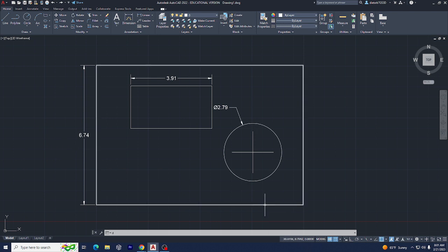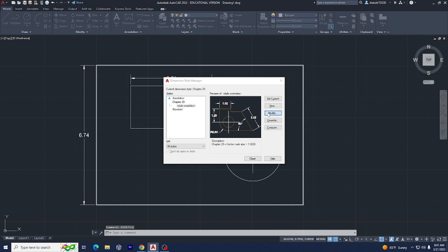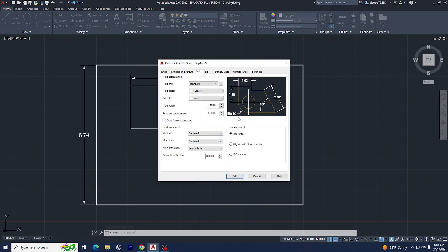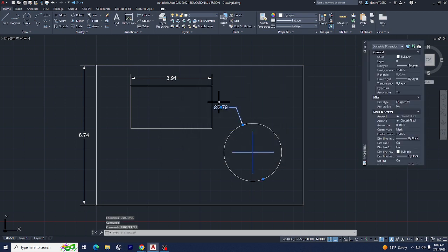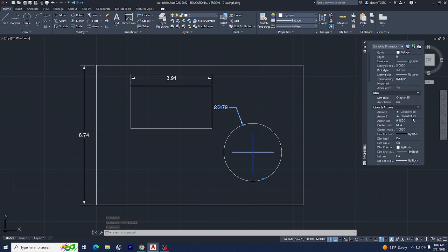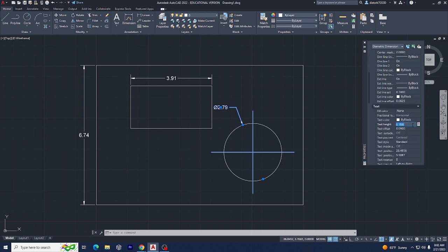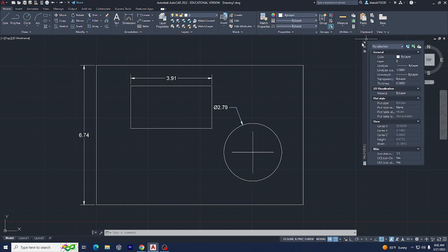So when you go to the dimension style and you go to modify, this changes it for everything in the drawing. So that this will be your dimensions for everything in the drawing, not just the one you're working on. Where if you do the dim scale, it just does the one that you're working on at that moment. And you can change sizes of them that way, or you can use properties. That's another way to do it. So say I want just this dimension to be a little bit different. I click on it, do properties, and then line type scale is 1. I can change it to 3. Center mark, you can change the size of the center mark on that. Change it to 2. Now it's much bigger. And you can change the text height to 0.5, and now it's much bigger. So you can do all that under properties as well. But I don't want to do any of that, so I'm going to close them.